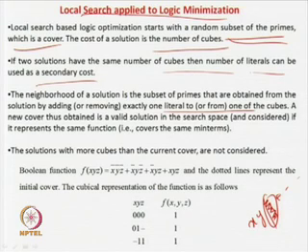So, as I told you, another way of finding the solutions could have been another random subset of prime implicants which is valid, and you keep on doing it till you get the minimal number of prime implicants. That can also be one of the solutions. One way of doing the local search. But now what we are doing here is slightly different. In this case, we take a random subset of prime implicants, then we take one cube and remove at least one literal from it. So, removing one literal means we are actually trying to get a minimum number of solutions.